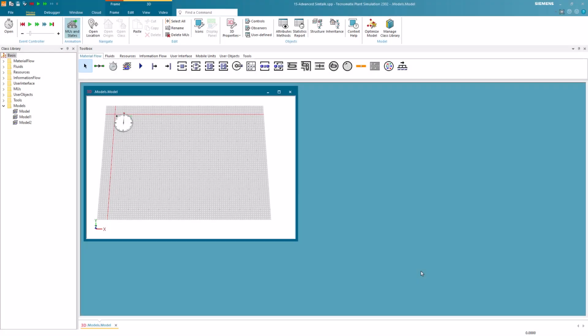In this video, we will dive deeper into SimTalk. The first topic we want to introduce are parameters. You can pass values to a method when the method is called. These values are called arguments. You then have to declare the same number of parameters within the method, and these parameters have to have the same data types as the passed arguments.